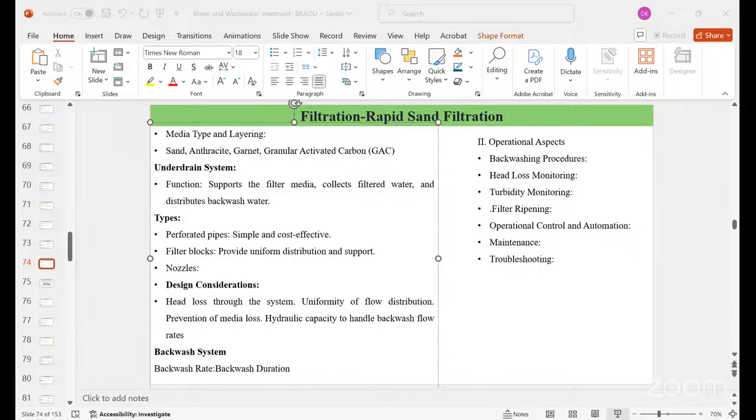There is a slow filtration rate, where the water slowly flows through the sand and allows ample time for biological purification, where the microorganisms play a key role in breaking down the organic contaminants. As for applications, it is mainly suitable for smaller communities, rural areas, and developing countries, and is effective for treating water with relatively low turbidity. With high turbidity, it will take quite a lot of time for the filtration, so it is not suitable for gray water and the like, only for very minute turbidity.